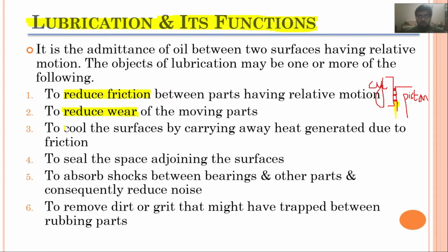So the next important function of the lubricant is basically to cool the surfaces. So it is not only lubricating, not only reducing the friction and wearing, it is also cooling the surface as well. It is taking away the amount of the heat which is being generated during the combustion process. And the next function is to seal the space between the adjoining surfaces. Means it is providing a sealing between this cylinder and the piston,